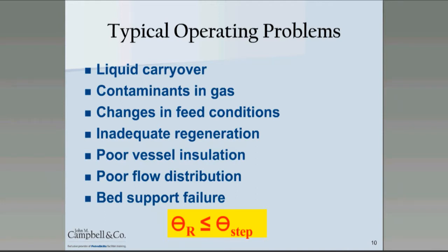Sometimes low points in your feed line can collect liquids that will then be carried over into one or more vessels during adsorption. Liquid carryover can cause both a slow, steady leakage of water in the product gas and the need to change out the inventory of molecular sieve sooner than anticipated.